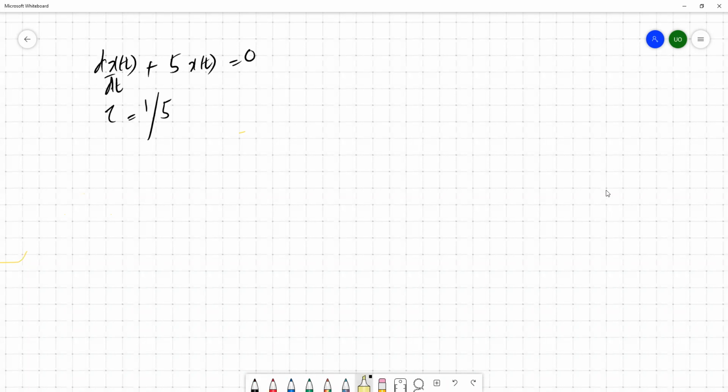By looking at the coefficient of the zeroth order term, you can easily recognize the time constant. So in the previous circuit we can easily identify the values of the resistor and the capacitor, because we have one capacitor and one resistor there. Without going into the differential equation, we can immediately evaluate the time constant, because we know the values of the resistor and capacitor exactly.